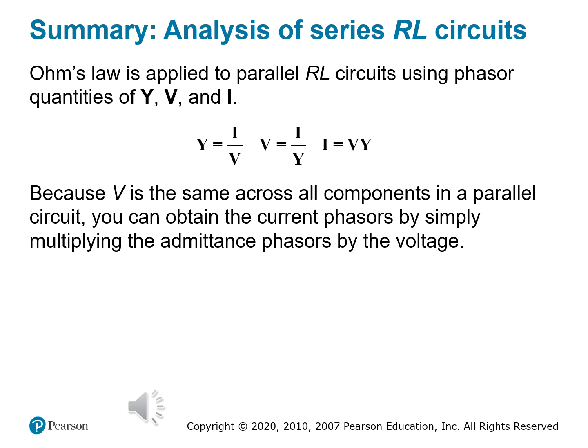You can analyze current phase relationships. You can determine how much of the current is real, again, in phase, and reactive, which is out of phase. And it keeps the math clean, especially when using admittance triangles like we did in the previous slides. So just remember this. In series circuits, the current is common, so you use impedance. In parallel circuits, voltage is common, so you use admittance.